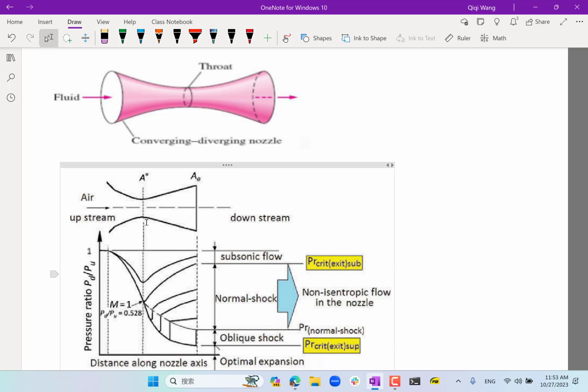When the Mach number reaches 1, we have the 1 over 1 minus M. That means even though at the throat the slope of area change becomes 0, the slope of pressure change as the Mach number reaches 1 is not going to be 0 anymore. So the qualitative relationship that as we reach the throat of the nozzle the pressure gradient becomes 0 now stops being true. We have a sharp corner over here.